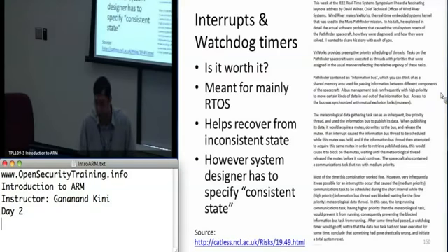What ended up happening was the meteorological data sampling task would get stuck doing something, and it would go into a deadlock. The watchdog would kick in and it would reset the entire operating system. This kept happening until they found out that they shouldn't be doing the priority inversion for that specific task, and they were able to fix it. So it's just an interesting example.